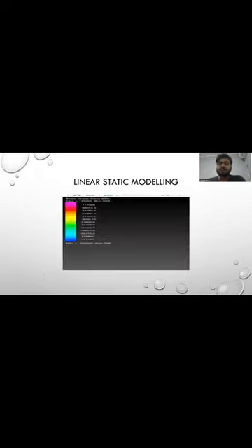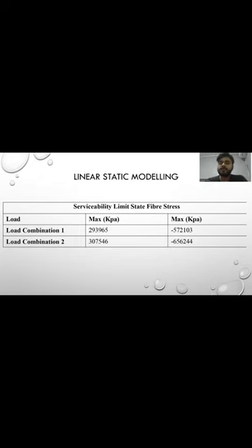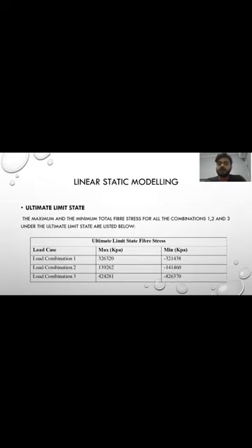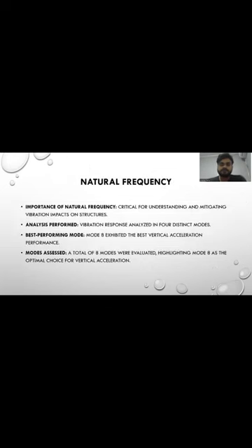In the linear static modeling, we did two models, ultimate limit state and serviceability limit state, and the maximum and minimum fiber stresses are given here under three load combinations.